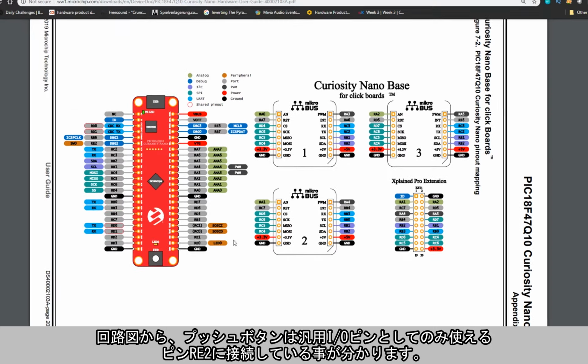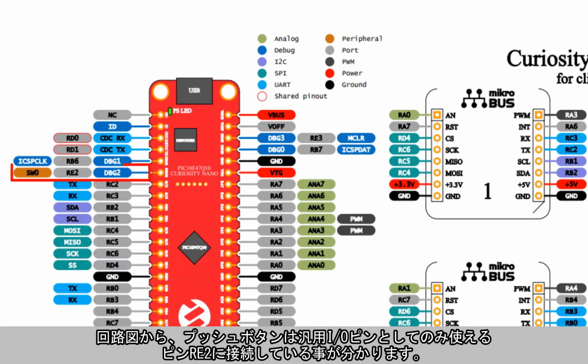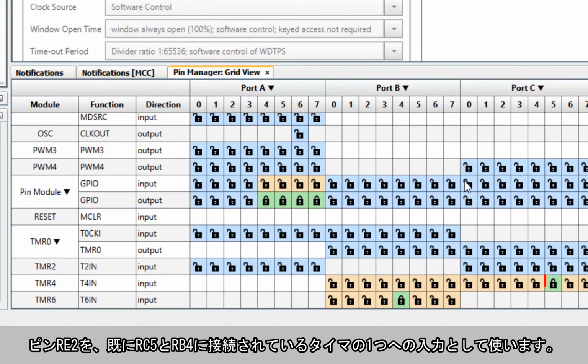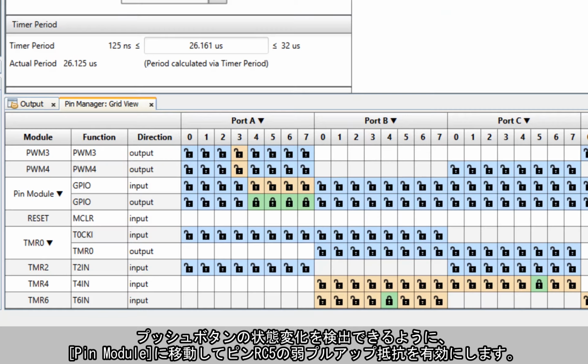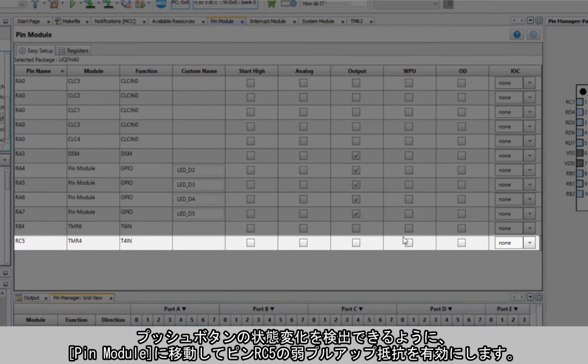From the schematic, we can see that the push button is tied to pin RE2, which is only usable as a general purpose IO pin. I want it to serve as an input to one of the timers that are already tied to RC5 and RB4. I'm simply going to tie the Curiosity Nano push button on pin RE2 to RC5 using a jumper cable. This means I'll also need to head over to the pin module and enable a weak pull-up resistor on pin RC5 so we can detect a change in the push button.